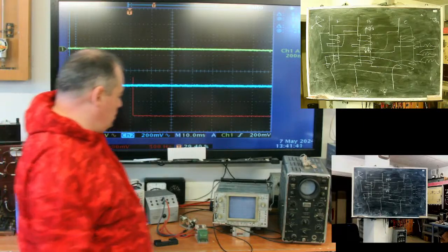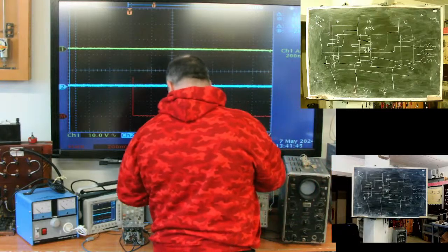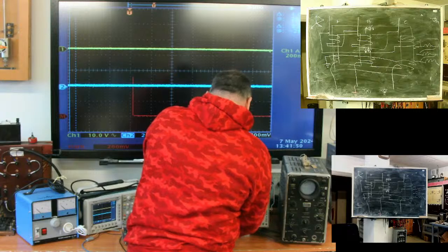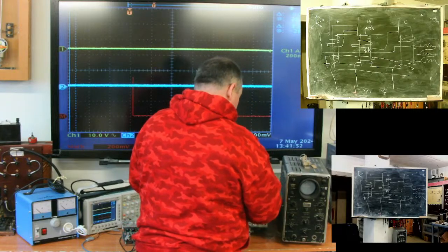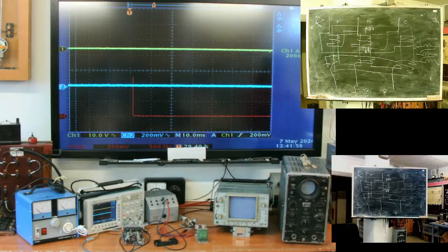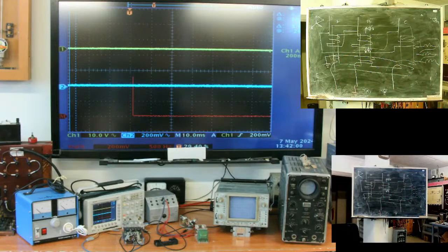So, conclusion. If we have a steel core transformer, to receive harmonic voltage at the output, flux should be harmonic, but because of non-linearity of the steel core, the magnetizing current will contain a third harmonic, will be non-harmonic.